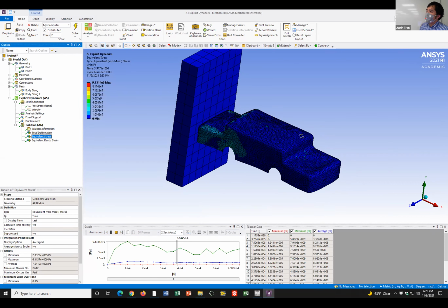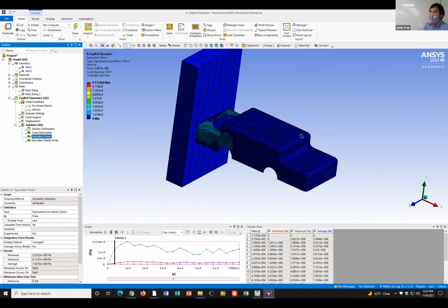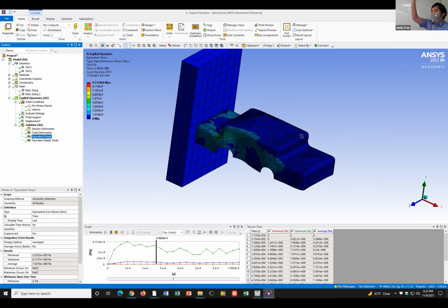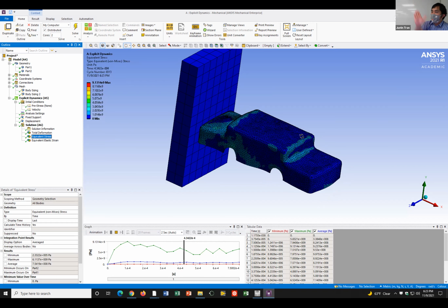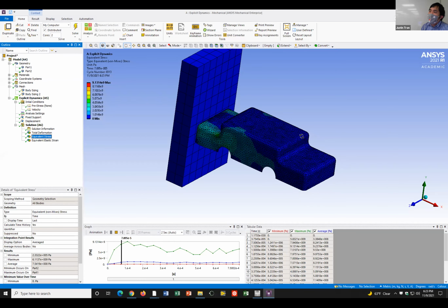What you're saying is that it's not representing the metal. The main thing is we're not representing buckling. We're basically assuming that the material is a linear elastic material. So what's happening is that when the car impacts, it goes up that stress strain curve, and when it's done, it just comes right back down that curve. There's no plastic deformation, no buckling or anything happening. And that's mostly for cost reasons. If we turn that stuff on, you would get a more realistic simulation, but it would take a lot longer to solve.